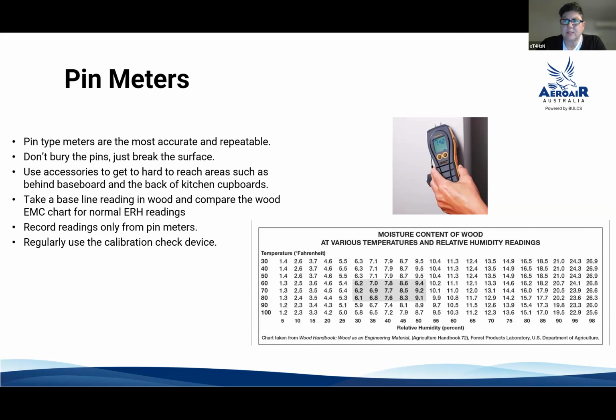A Trotec looks more at gravimetric readings. Their CME5 only looks at gravimetric readings, so they balance their meters through reading and measuring concrete. That's their baseline. So you can understand that as much as the Protimeter is really good in some ways, sometimes the Trotec is actually better.